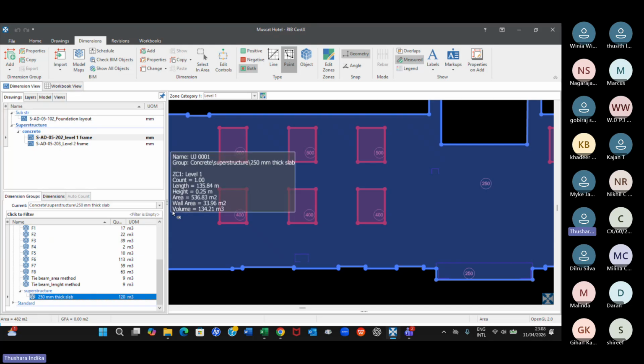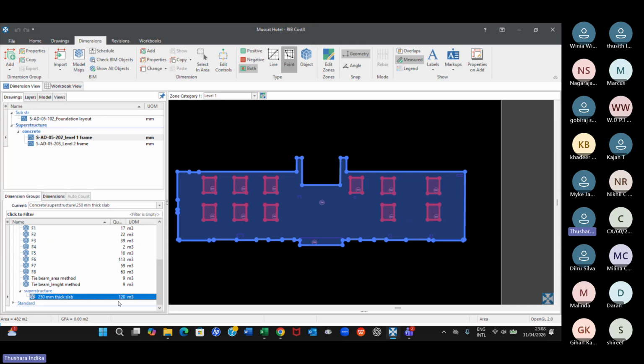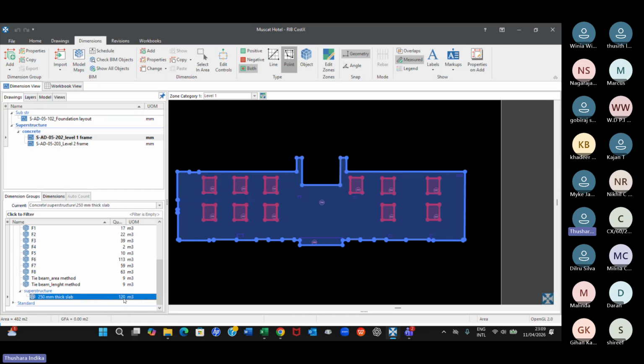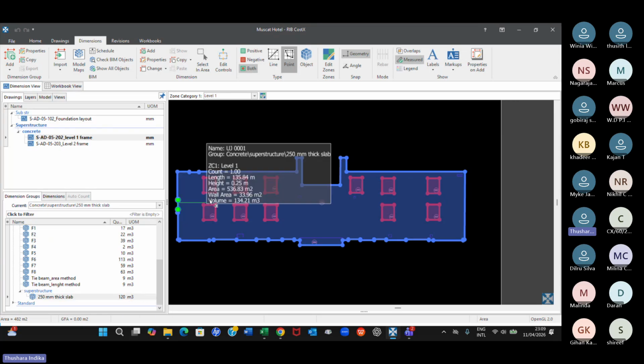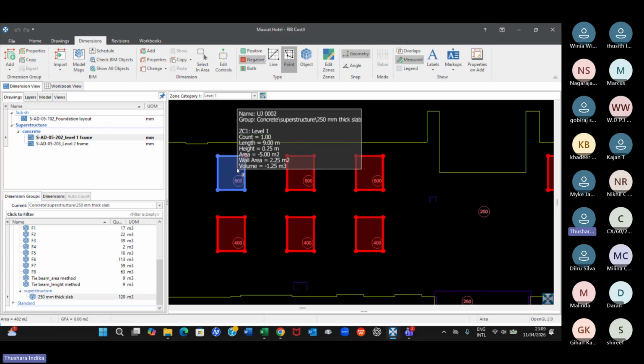It's not like we calculate the entire area first and then multiply it by another thickness. No, thickness is automatically multiplied internally. When we measure an area, what we get is volume including multiplying by 0.25. So when I deduct this area, that is also the same case.